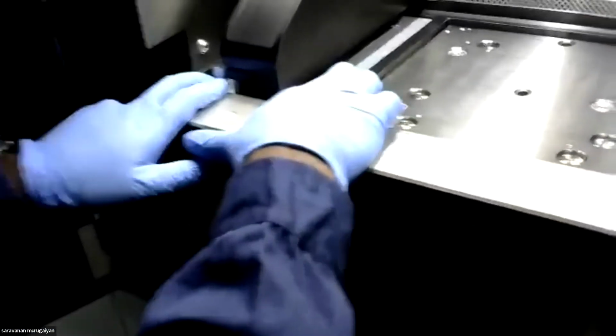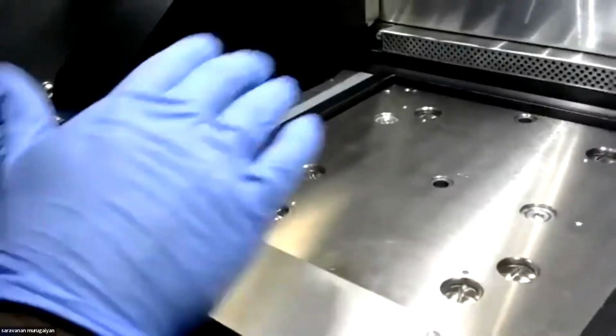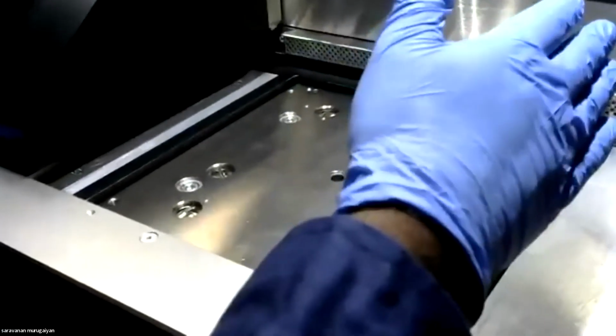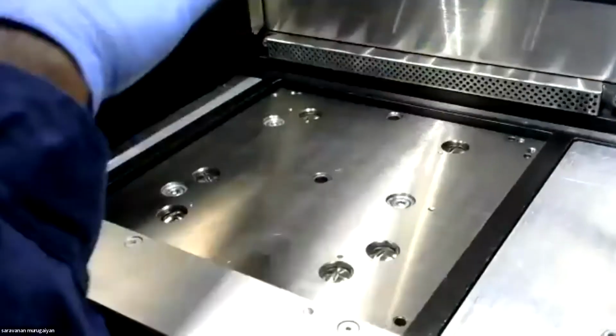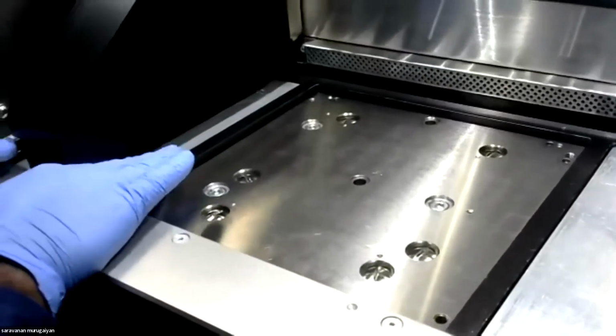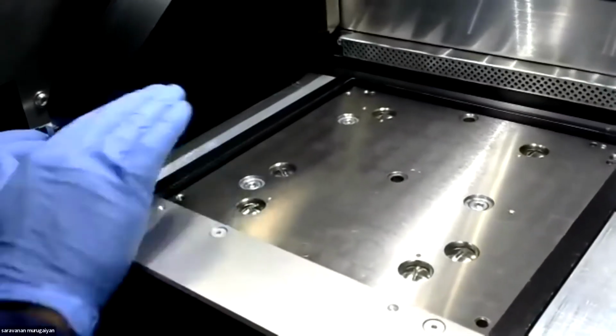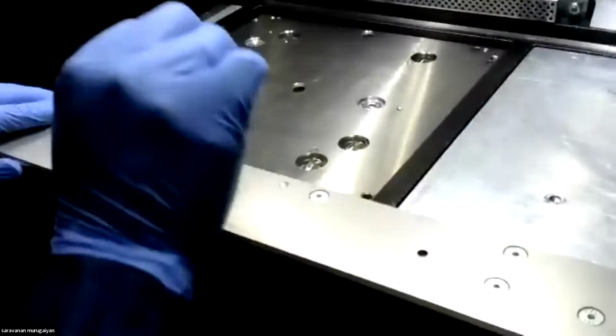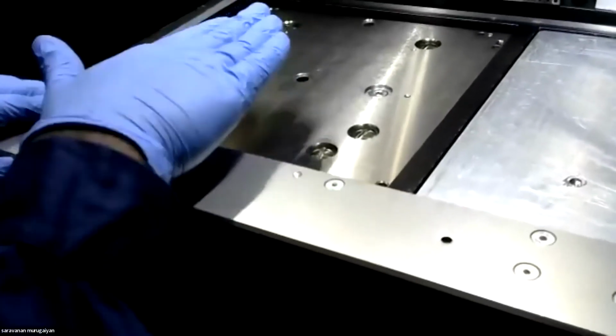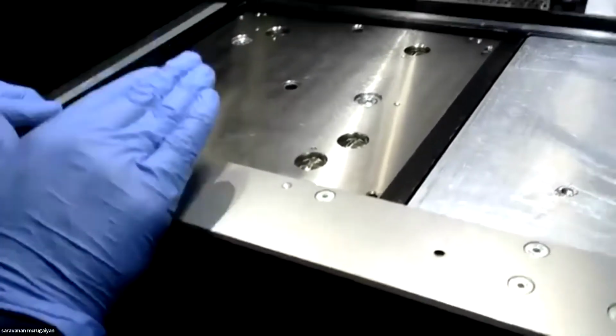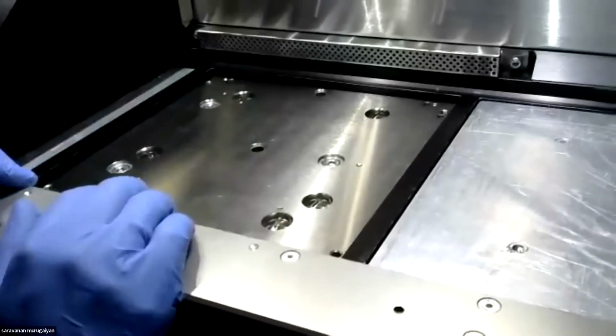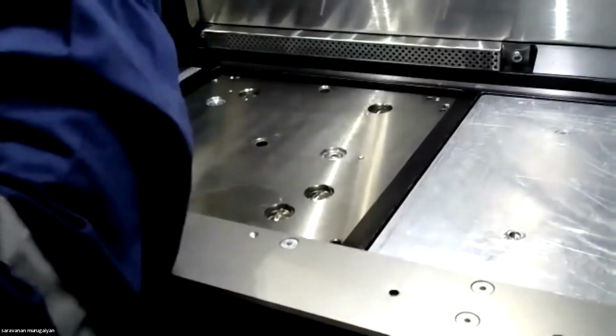Now on the left there is another platform. You can see this is the collector platform. The excess powder which comes from the dispenser platform goes into the collector platform. So usually the waste powder falls onto the collector platform, and the thin layer of powder which remains on the base plate gets exposed to the laser source. The laser source is at the top.